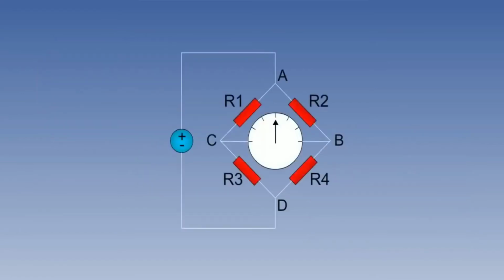To measure electrical resistance, a resistance circuit is employed, commonly known as a Wheatstone bridge. We can see here a diagrammatic illustration of a Wheatstone bridge circuit. In basic form, the circuit consists of a power source and four resistors, labelled R1, R2, R3 and R4 in our diagram. For a given voltage input, the current flowing through the resistors will depend on the resistances. If the resistances are equal or balanced, the current flow in the circuit will be zero.